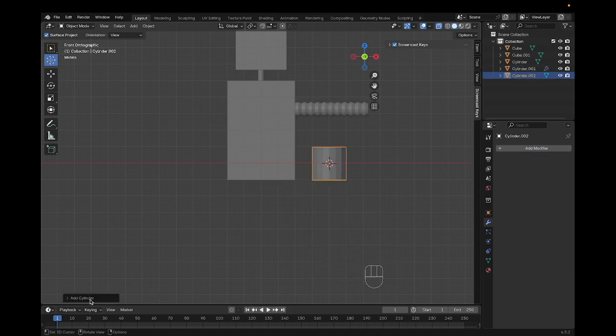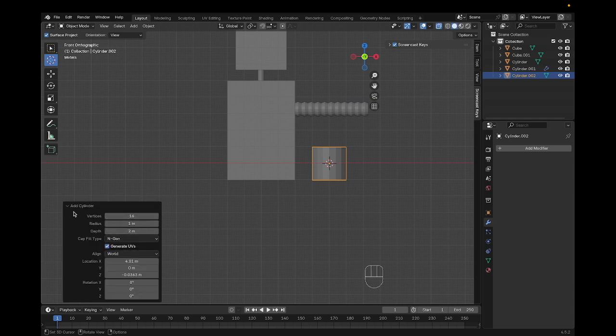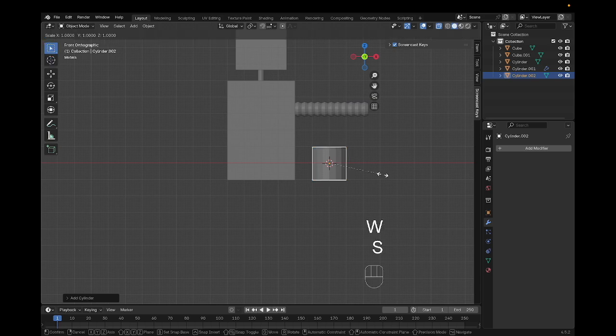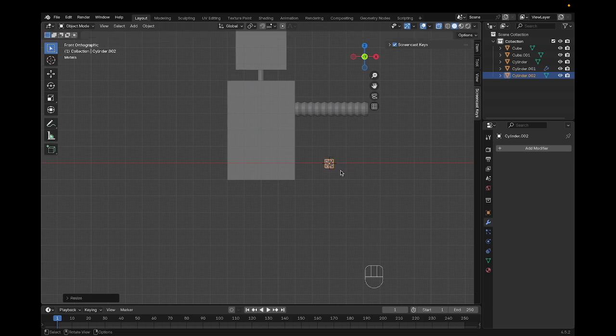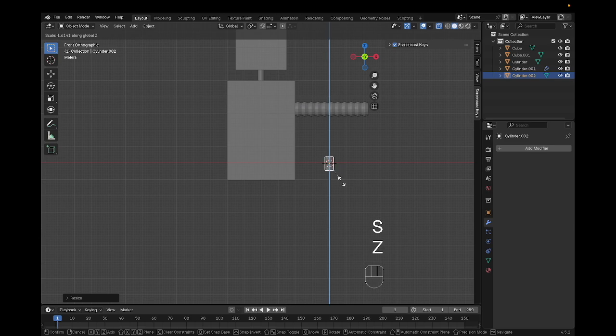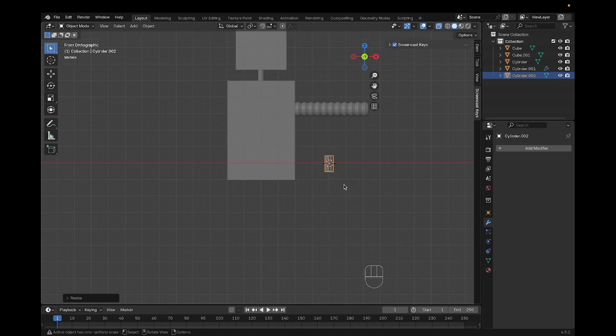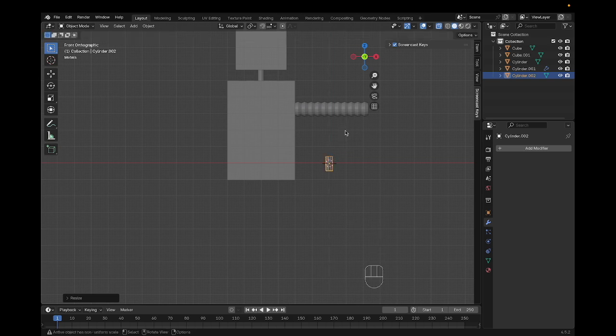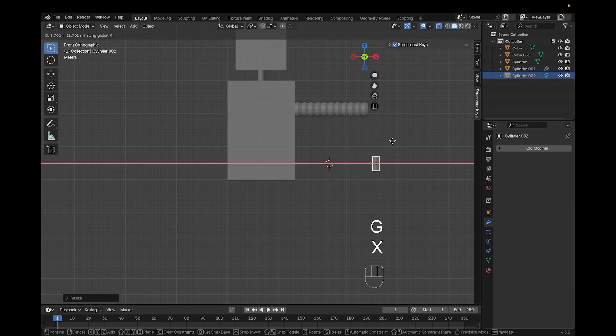If you're wondering, once you change the vertex count, that becomes the automatic default for this Blender file. Now we're going to scale it down to pretty small, about the size of your neck. Scale on Z axis. Sometimes I change it all the time, just because once it's bigger, I'd rather it taller, I'd rather it thinner or whatever. So now we're going to grab along the x-axis, rotate along the y-axis at 90 degrees.